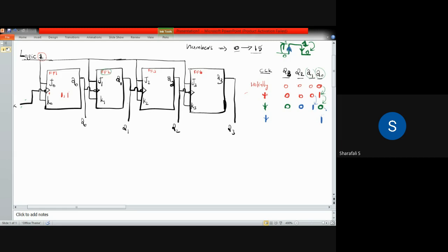Okay, so this time 0 to 1 means the positive edge of the clock pulse, which means that Q0 output is changing from 0 to 1. So that Q0 will be acting as the clock pulse of the second flip-flop. Changing from 0 to 1 means that it is in the positive edge, so we will not have any change at flip-flop 2, and Q1 retains its state, and we will get 1 here.